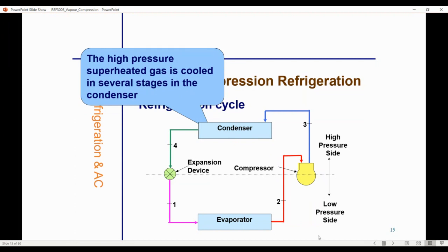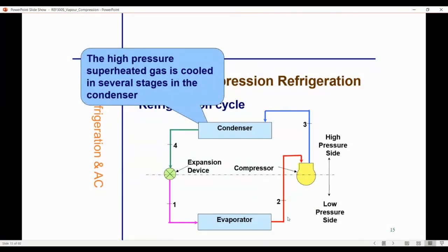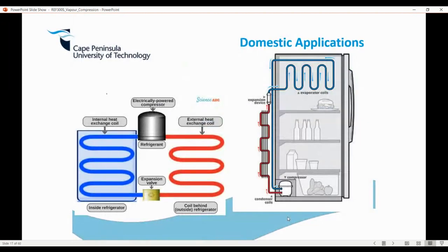Furthermore, we get into the condenser. Okay. So the gas gets rejected back into high pressure liquid, and we have an expansion device. Could be a thermal expansion valve, which not only reduces the pressure, and as Mr. Brill said, it controls the flow. It's a regulator of some sort, right? You can tell a lot from the expansion valve.